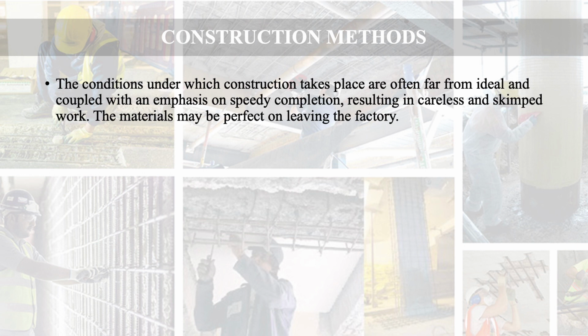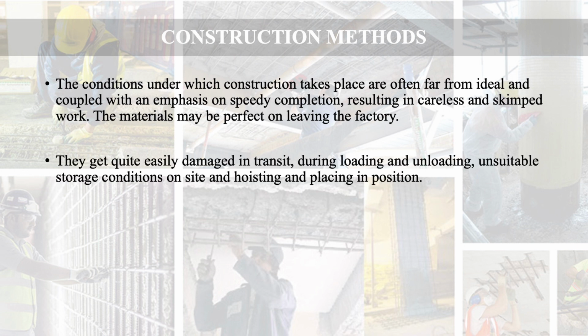The conditions under which construction takes place are often far from ideal and coupled with an emphasis on speedy completion, resulting in careless and skipped work. The materials may be perfect on leaving the factory. They get quite easily damaged in transit, during loading and unloading, unsuitable storage conditions on site, and hoisting and placing in position. So during all these activities, the material may be damaged or it may get defects.